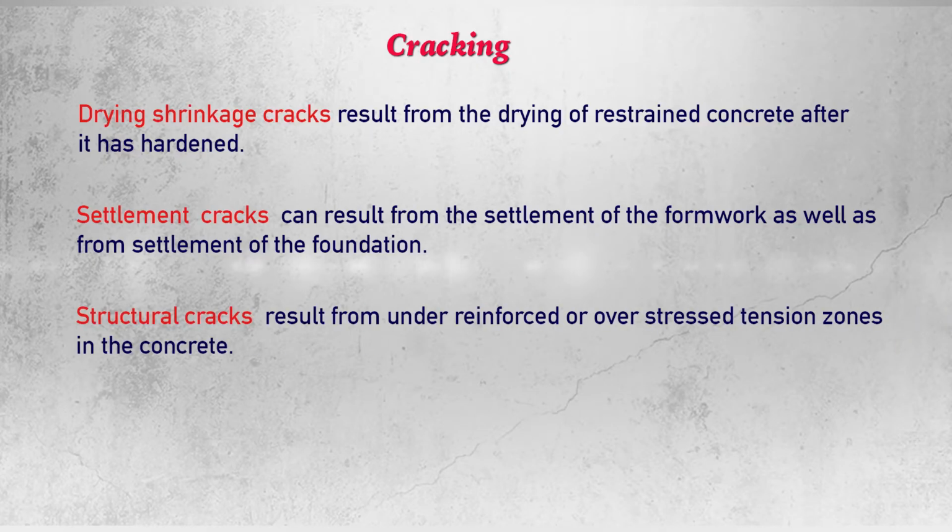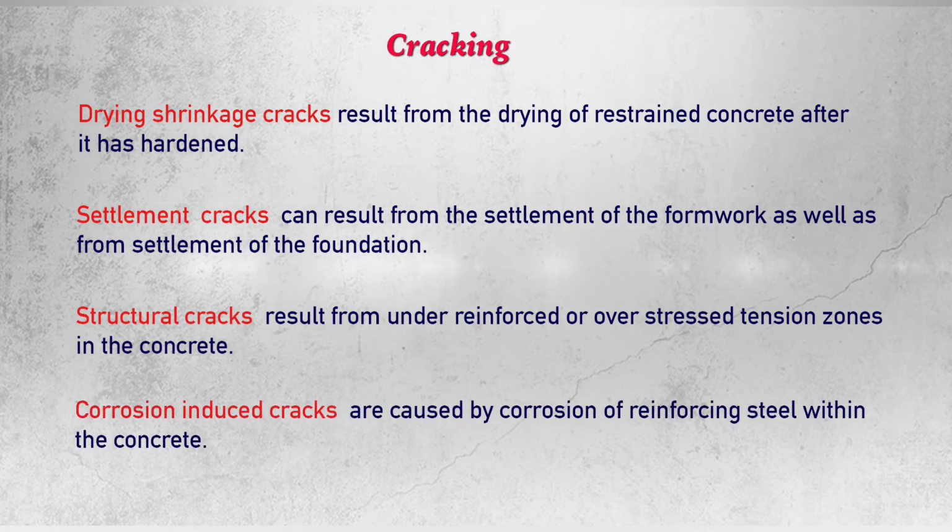Then there are other cracks like structural cracks. Structural cracks result from under-reinforced or over-stressed tension zones in the concrete. Corrosion-induced cracks are also there, and these cracks are caused by corrosion of reinforcing steel within the concrete.